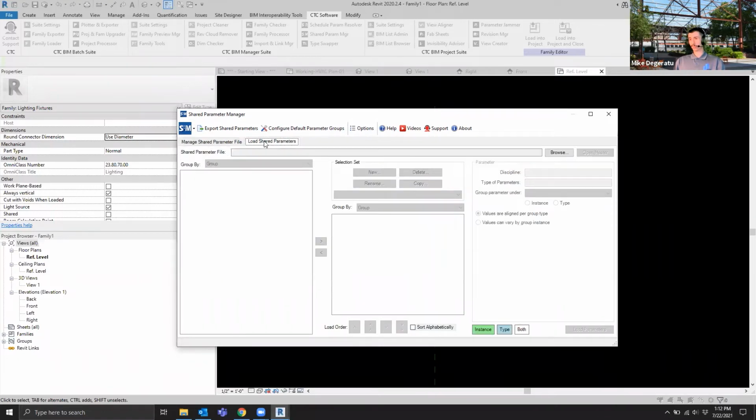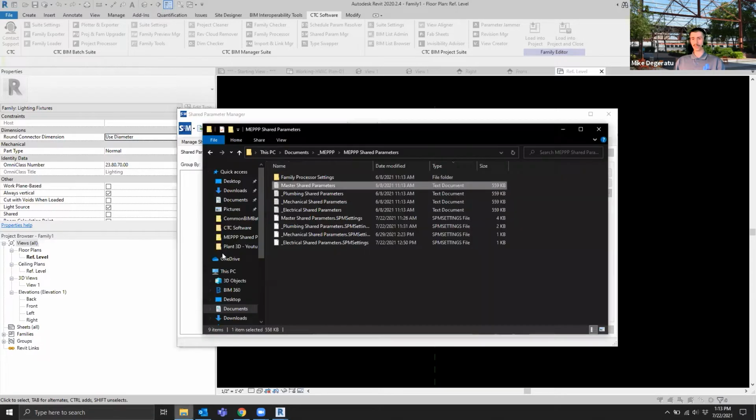You could add, you could remove, makes it very easy to modify share parameter files on the go. But for our example case, we're going to be loading parameters into the family. So in here you see it is blank, and you have some of the normal stuff you see whenever you start creating parameters. This is actually in Revit. But up here, you would have your share parameter file name.